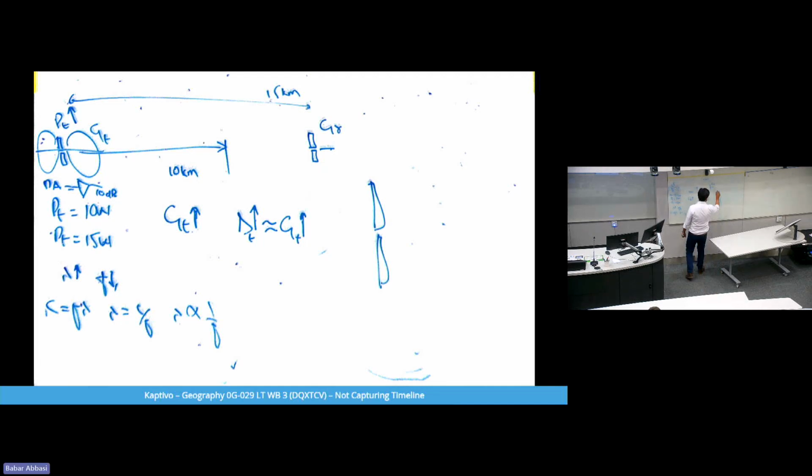Okay, so one reflected plate. What we have learned from reflected plate, if there is a ground plane, what will happen? Mirror effect. If I have a reflected plate on the back side of a dipole antenna, then what will it create? It will create a virtual dipole antenna. So it means that I have created two dipole antennas now. That's an array of antennas. Now there are two elements.